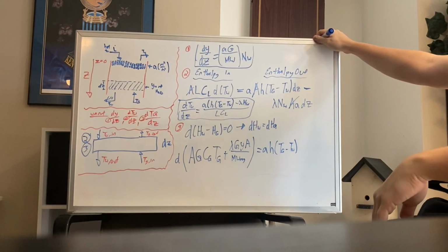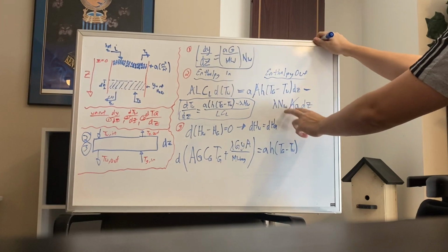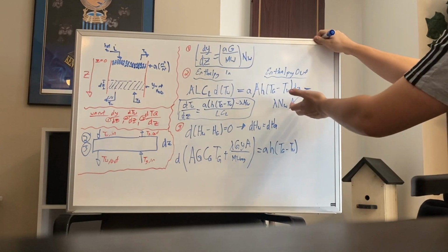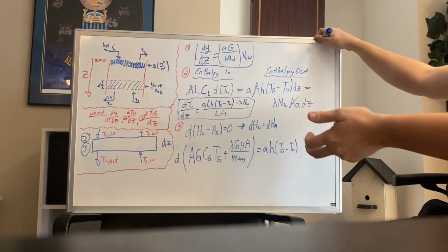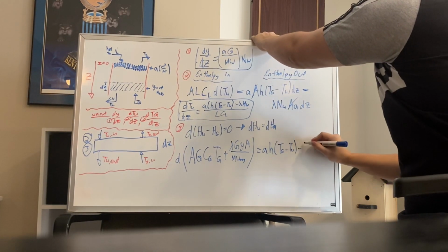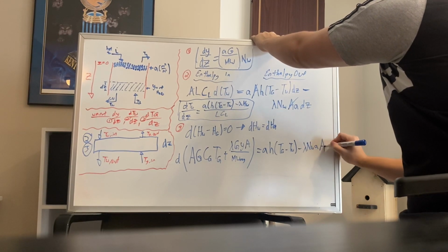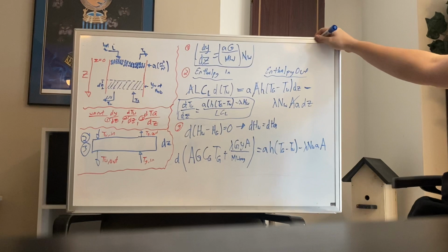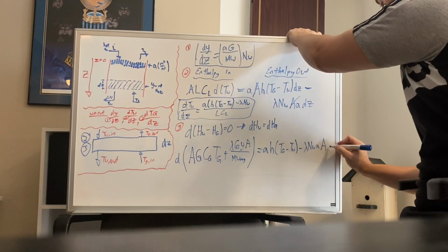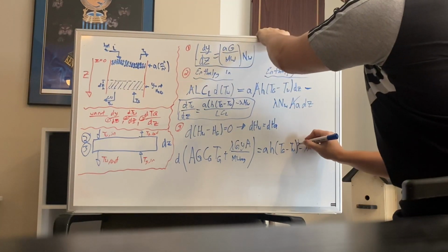And also we have to take into account, once again, this second set of coefficients and variables here, which is again taking into account that evaporation of the water into the gas phase. And so we are still going to have to add on this heat of vaporization multiplied by the molar flux multiplied by the specific area and the cross-sectional area. And so that's going to end up being equated to our outside. I also forgot the dz. There should be a dz on this one too.